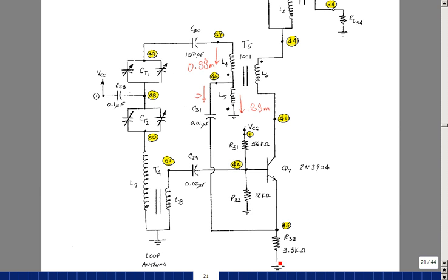So nothing comes into this resistor from the capacitor. Now, with current going out of the dot in both these coils, it's trying to have current come into the dot on the coil on top, just like before. But now we've taken that level off of this resistor, R33, and current begins to flow down this path. The value is about 0.11 milliamps. So now I've established a current down this path. The transistor amplifier is now going from cutoff to actually the active region.